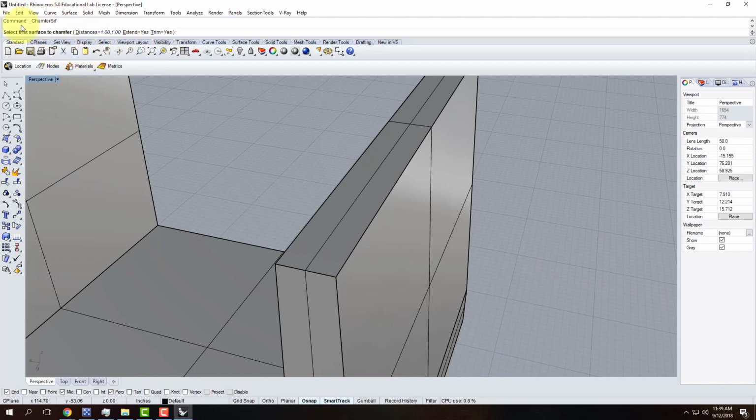Now, before I actually do any chamfers, I need to adjust the distances. And what it means by distances are, if I was drawing it, sometimes it's easier just to draw, and I had my corner like this, and I want to clip the corner right here, the distance it's referring to is this distance and this distance here. Typically they're even. The one outside is even, and the one outside is 1/2 inch and 1/2 inch. Right now it's asking me for 1 inch, so I'm going to change it to 1/2 inch to match that. This doesn't have to be symmetrical. You could do 1/2 inch by 1 inch or whatever it is that you wanted conceptually.